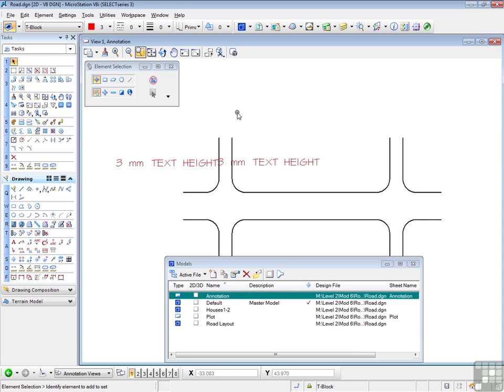And look what's happened. I have my 2 text strings. There's 1, there's 2. This is the left justified text. This is the right justified text. What I'm trying to show you here is what happens when you scale from the 3mm height. Imagine lots and lots of text strings all over this drawing, all placed supposedly at best advantage in relation to the drawing. Scaling up this way makes quite a mess of the text placement. And again, in a congested design, this could be pretty disastrous.